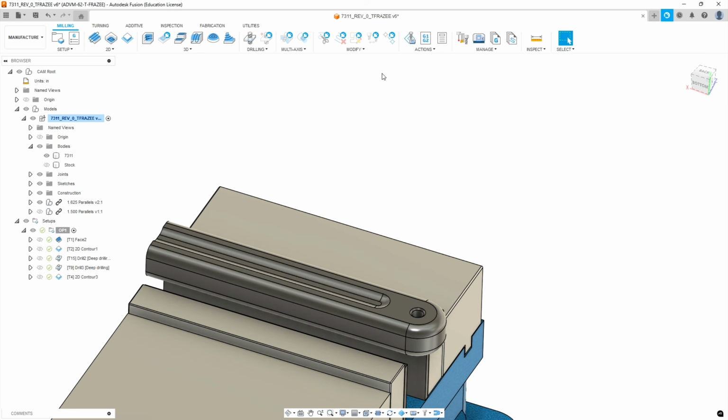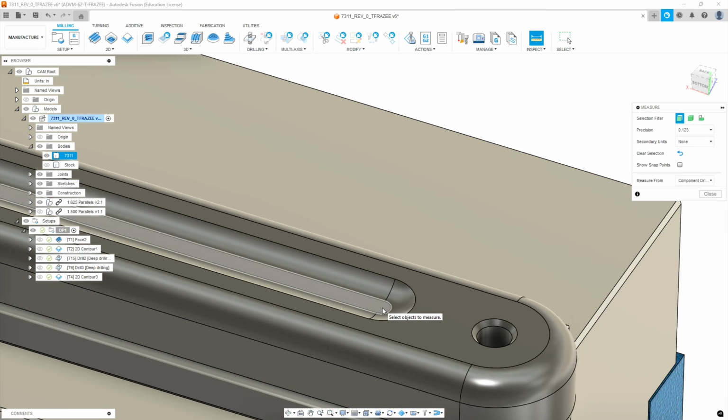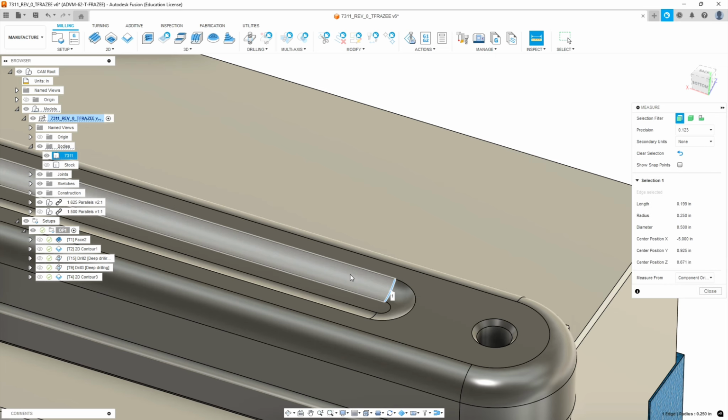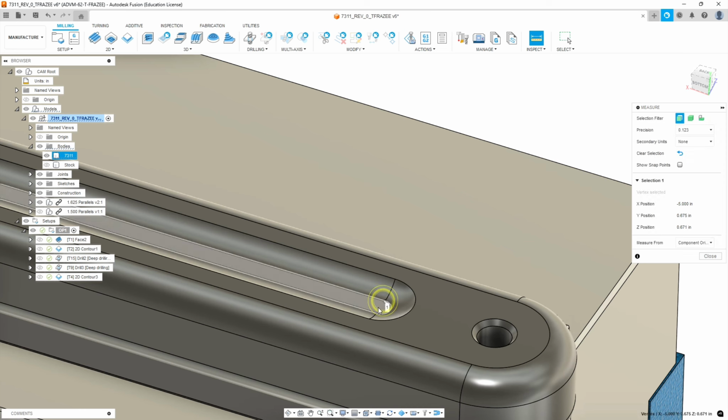Now, the little flat here on the bottom, the most efficient way to cut this would be to cut this flat with an end mill, and you come back with a ball cutter that's the diameter that results in this radius here. So if you recall, that's a 1/4 inch radius. So a 1/4 inch ball cutter cutting on center should be able to easily make that feature. Problem is, we don't currently have an end mill in our library that can cut this flat.